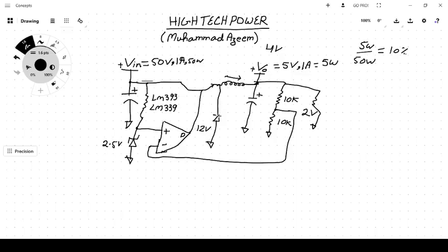So by inserting a diode, what happens is that when the transistor is on, switching as saturated, here would be the total input voltage, which is positive, and if there is a positive voltage on the cathode side, then the diode is reverse biased, and due to the reverse bias action of the diode, no current would flow through the diode, and all the current would pass through the inductor just as normal. But now suppose that the transistor is off.